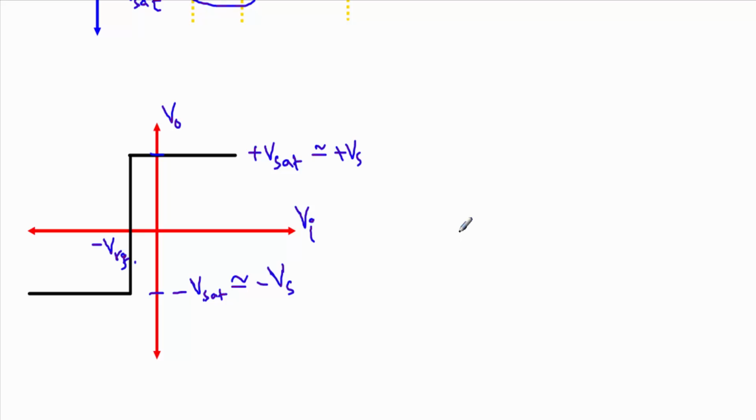And let me show you the transfer characteristics. Here our reference voltage is at this position, the negative reference voltage, because this is our 0 point, this is our input voltage axis and this is our output voltage axis. The points that are lying to the right of this negative reference voltage point, that means in that region our input voltage Vi is greater than the negative reference voltage.